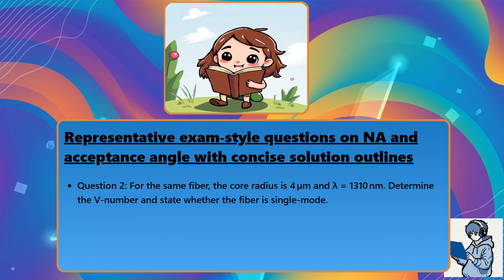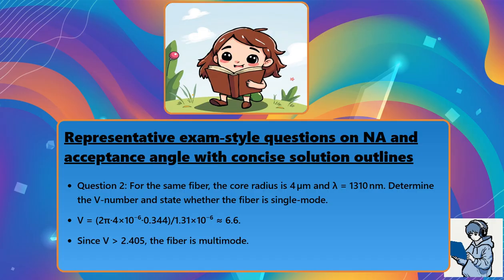Question 2. For the same fiber, the core radius is 4 micrometers and λ = 1,310 nanometers. Determine the V number and state whether the fiber is single mode. V = 2π × 4×10⁻⁶ × 0.344 / (1.31×10⁻⁶), approximately 6.6. Since V is greater than 2.405, the fiber is multimode.